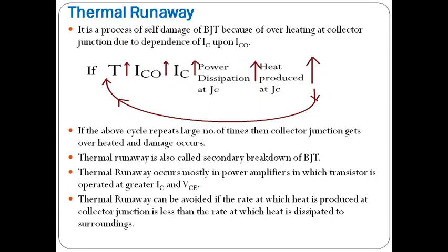Whatever maximum power rating the manufacturer has given at the collector junction, it should not be exceeded. When it exceeds the maximum power rating of the collector junction, more heat will be produced at the collector junction. Due to this reason, thermal runaway will occur.